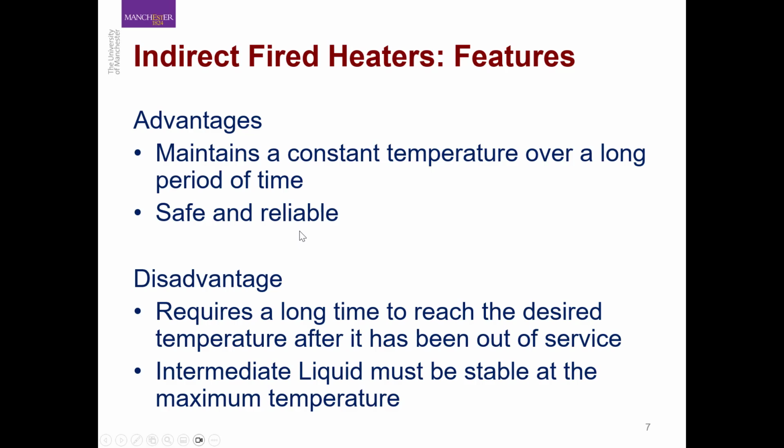Reliable, as I explained, in that it can keep working, for example, even if you have a problem with your flame or with your burning of the fuel. And in terms of safe, in the sense that you are not directly heating your process fluid, if you have a process fluid that contains, for example, flammable gas or a system that can cause fire, then because you are using an intermediate fluid, you don't have to worry about the fire in the process or in the system.